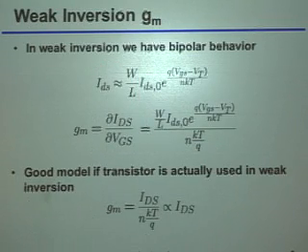Okay? And the reason for that is, as we talked about a lot last time, when you get into subthreshold, the CMOS transistor actually looks like a bipolar device. So when you get below that threshold voltage, the drain current versus gate to source voltage has an exponential relationship. And just like we said before, from a functional standpoint, GM is always just the derivative of the drain current with respect to the gate to source voltage. Nicely enough, if you have an exponential behavior there, then when you take the derivative, you just get back another exponential, just scaled by some factor. So in particular, and again, I hope all of you have seen this at least once or twice before.